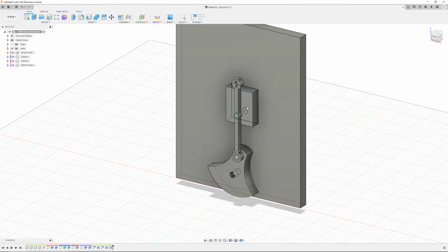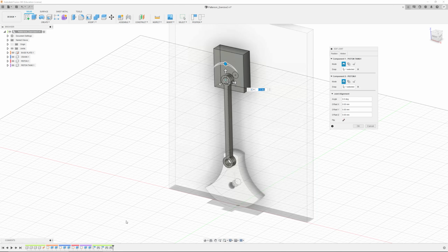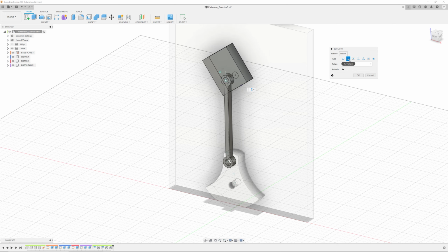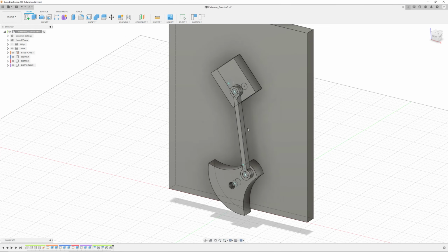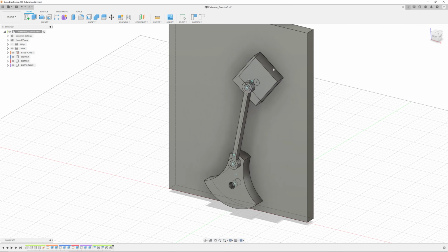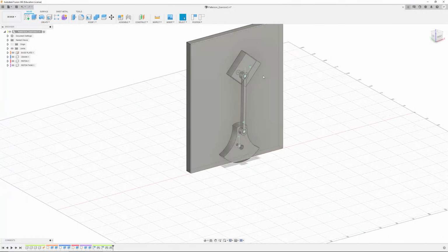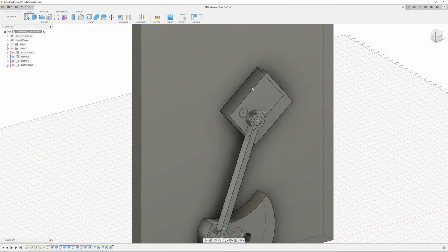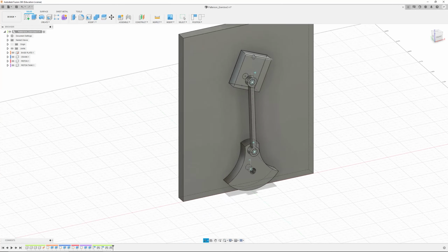So you can see there how it's misbehaving. So I'm going to go ahead and edit that joint, change it to a revolute. Still not working correctly. It does need to revolve, but it looks like what I actually need is to also lock it in another way.